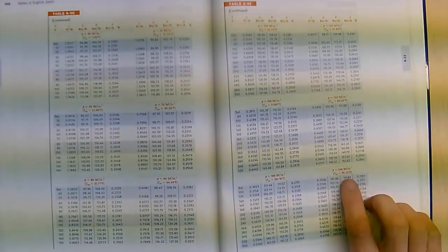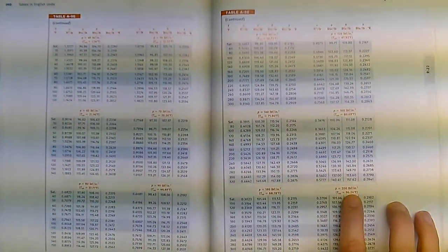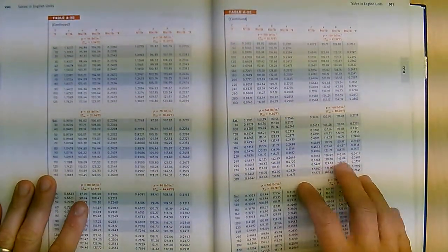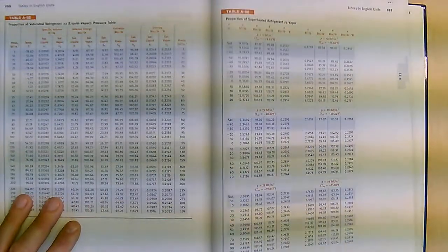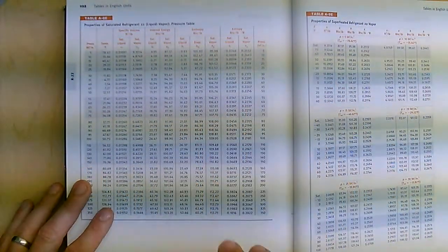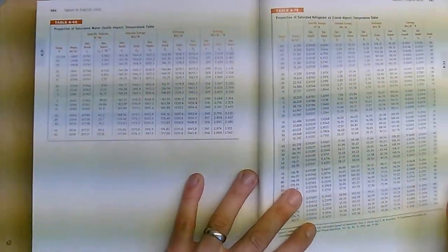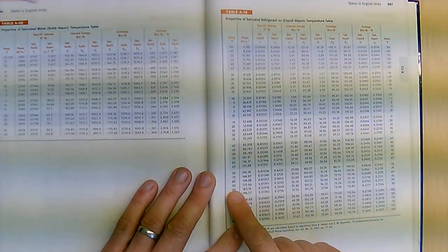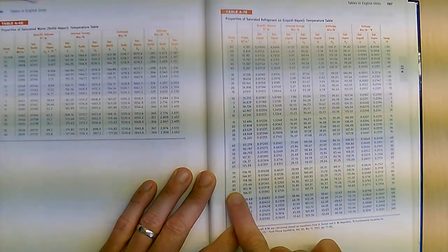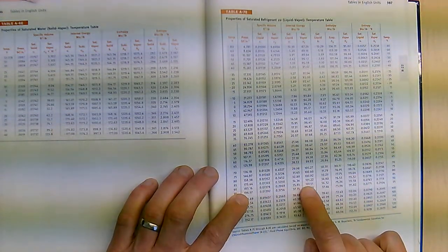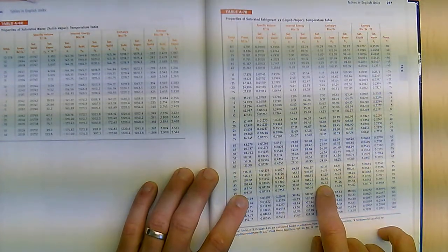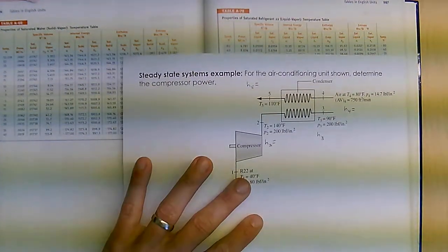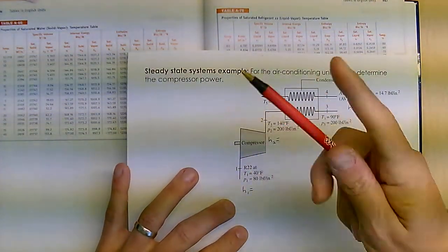Now again, you remember the saturation temperature at 200 is 96, so I'm actually below this. I don't have liquid, I am a liquid. I don't have a liquid table, so what I do is I approximate it as a saturated liquid at the temperature of 90 degrees. So I go into my temperature saturation table, I go down to 90 degrees, and I use my H value right there, which is 36.32. So let me jot down these values before we move on and deal with the air.